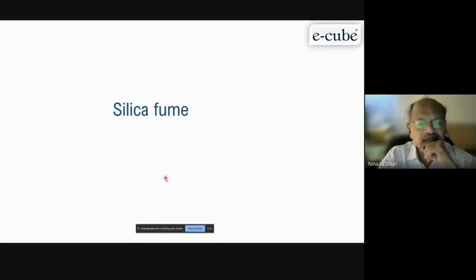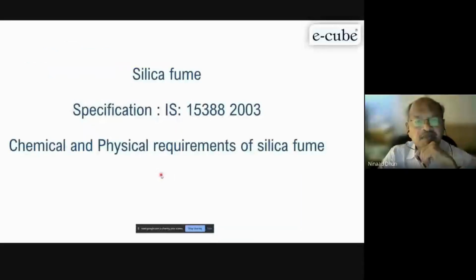First we discussed fly ash and then GGBS. For their replacement levels, fly ash can go up to 35% replacement of OPC. GGBS, as per IS code, can go up to 70% replacement, and in some cases people also use up to 80% replacement, meaning 20% OPC and 80% GGBS, since it has hydraulic properties also. Now silica fume is used in a percentage ranging from 4% to 15%. In the general case about 5 to 8%. In specific applications we can go up to not more than 10%. So we must always remember this about silica fume, a supplementary cementitious material.